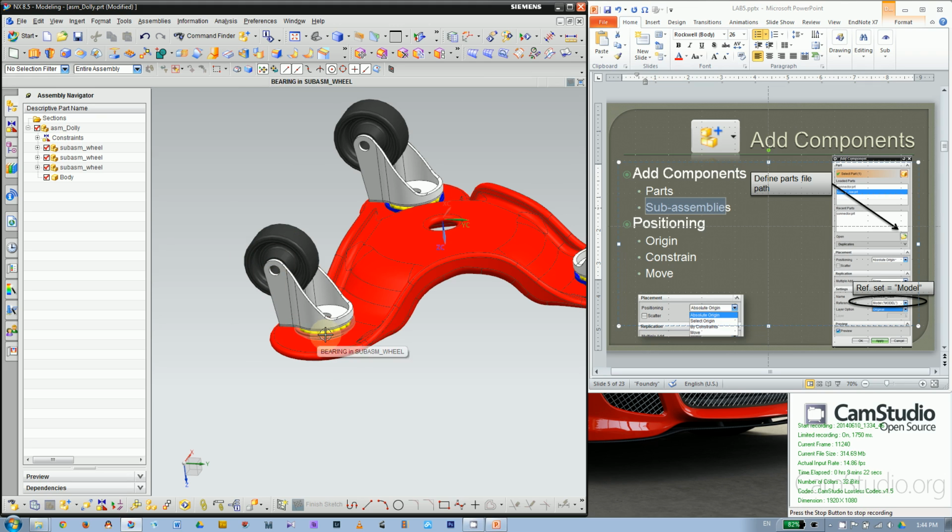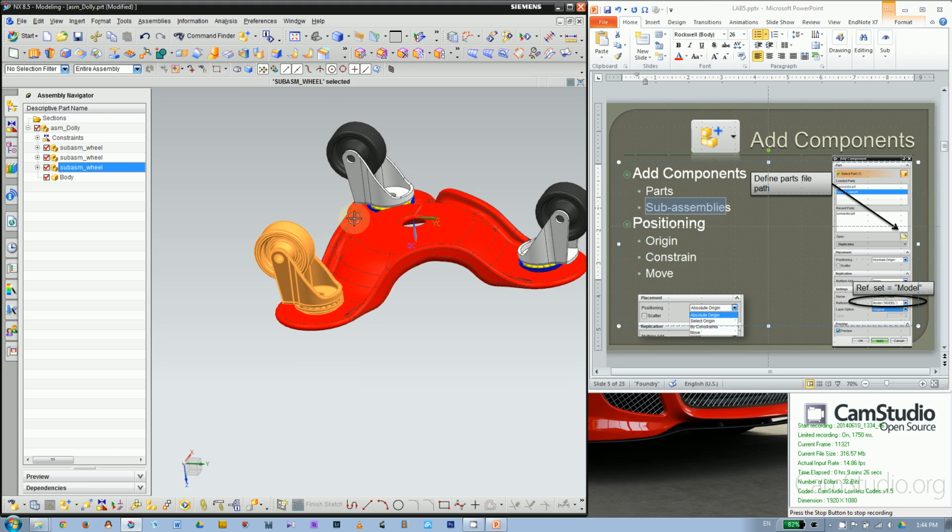Make this one sub-assembly like this, so you don't have to insert three times for the same components, which is here. So many components here, right? And of course, you can insert another sub-assembly under this level too. So it really depends on your application.